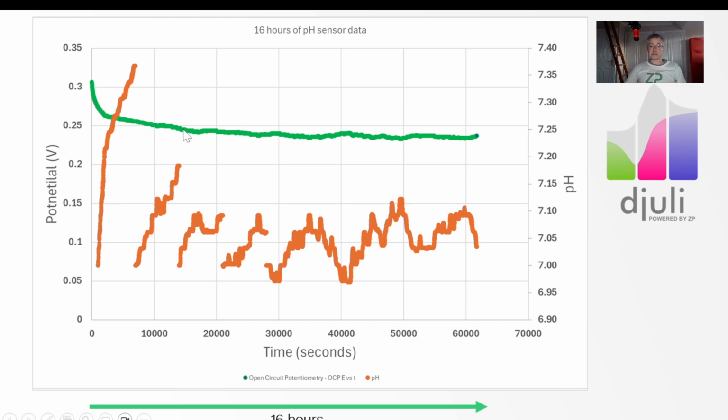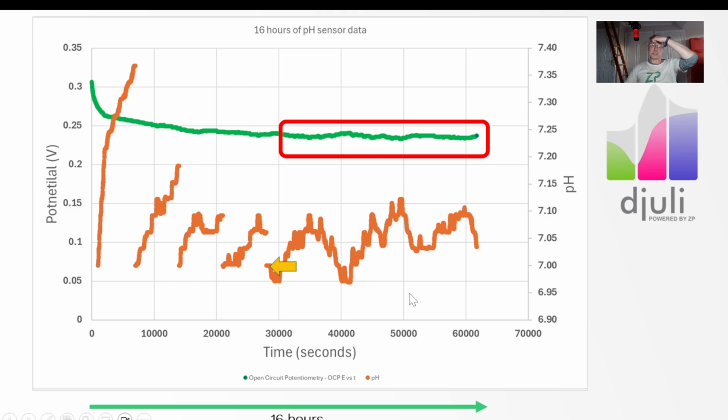At which point we start to realize that you can see in the raw data that these sensors equilibrate, and that's understandable. You're leaving it in the system, and it is generally equilibrating. Most of the change actually happens earlier on, so you can see that by about a third of the way through this 16 hours, we've more or less formed an equilibrium, and at that point we don't bother to calibrate again. So for the last 5,000 seconds, which is about 8 hours actually,